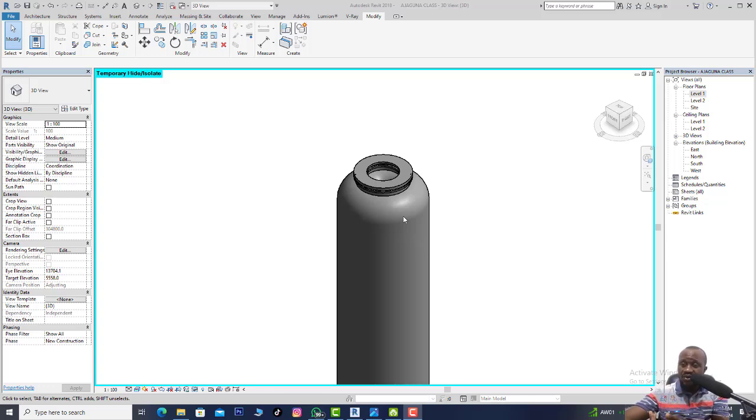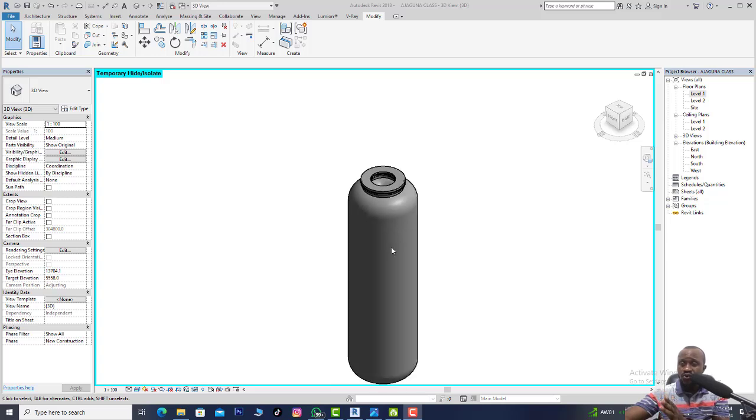Then after which I'll be teaching you how to create a pipe and the flanges, and to connect the various pipes to this tank, and maybe if there's another tank that I'll be creating. Okay, so this is how to create a tank. You can create any kind of standing or vertical tank with this method, guys.